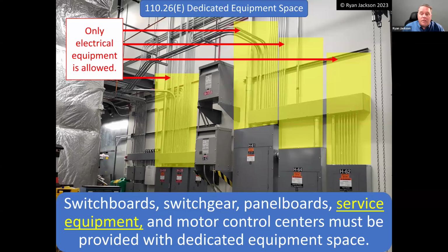And basically what it was is within that transformer, there was a failure. And I think what it did is it put primary voltage through to the secondary. And the splice that I took a picture of was not in a box. It was just an open splice because the electricians figured, it's low voltage, who cares? Well, as it turned out, obviously we should have cared because it was a problem. But yeah, the ultimate cause was the equipment malfunction. It was the transformer.